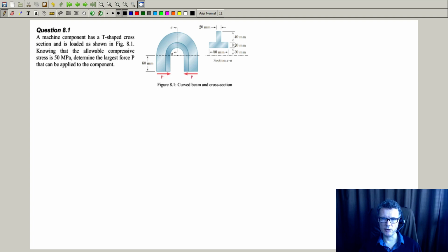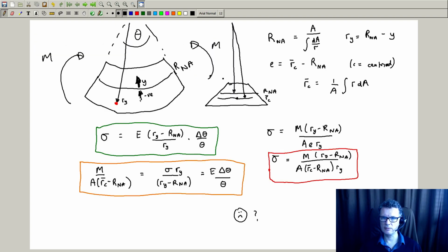the centroid, I suppose. So if we go back to the equations we got, we want to do the centroid. So here, if we're working with standard shapes, we can replace this with the sum of areas times R divided by the sum of area.